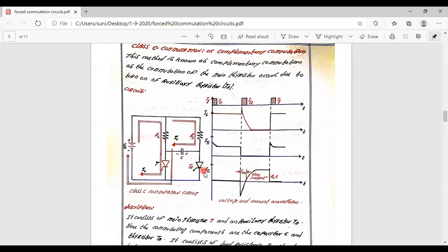So whenever you are going to consider this device, the device is going to be turned off as the other device is going to be, as both are going to be provided in parallel. When this device comes to the conduction, the voltage provided across this device is going to be nothing but the capacitor voltage, isn't it? Again, if this device comes to the conduction, then the on-state voltage drop of this device only appears across this until the capacitor is going to be charged.